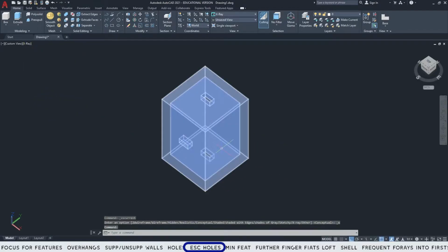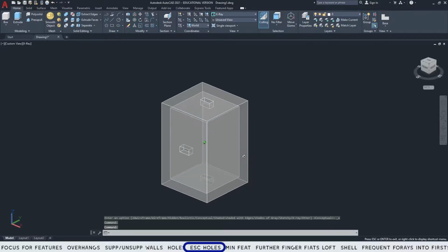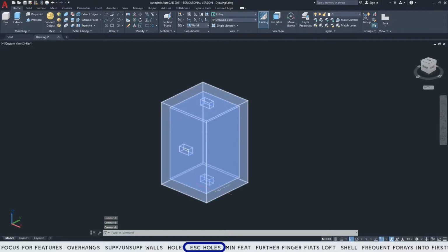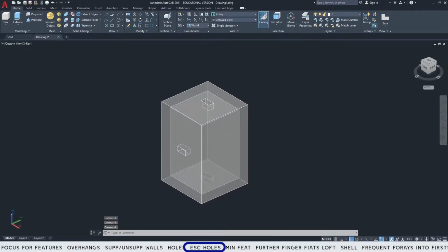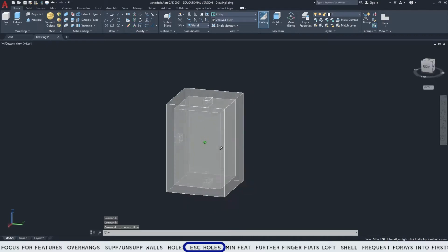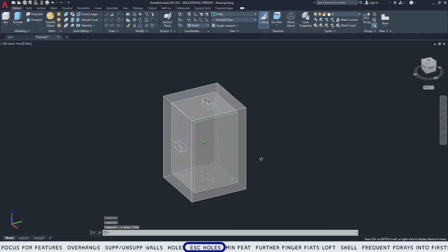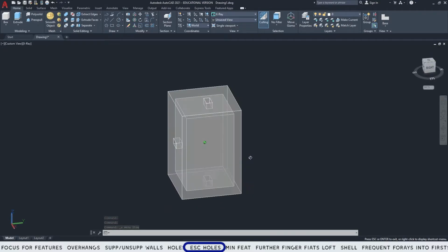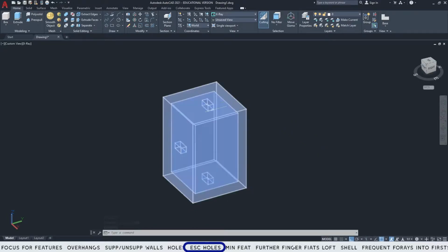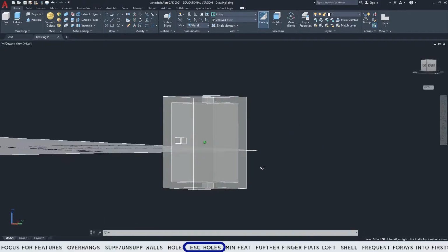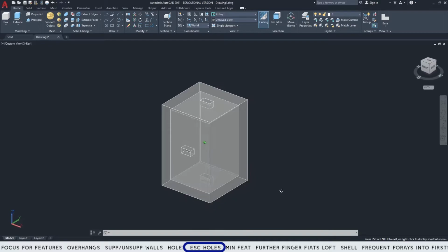All right, so this object is hollow, as you can see, and it's got 3 escape holes here. I won't call them escape holes, it's just the part has 3 holes built into the design. Now you can kind of tell, regardless of the orientation that it's going to be printed, it's going to require supports. The problem is that these holes aren't really big enough to allow you to remove those.